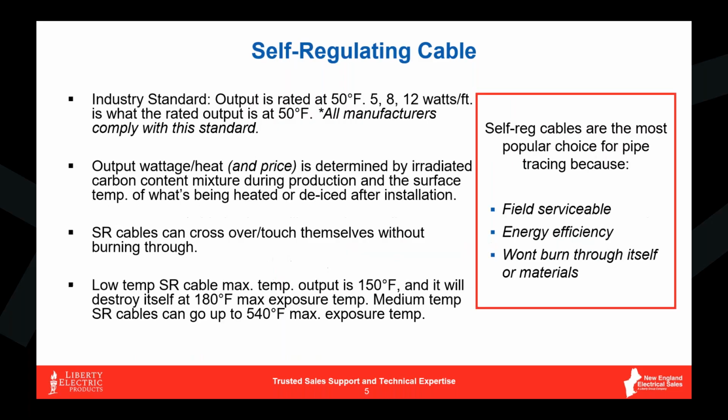So when we talk about self-regulating cables, there is an industry standard that all manufacturers abide by as to how much heat this cable puts out at the temperature rating of 50 F. So when you see the jacketing of a self-regulating cable where it denotes 5 watt, 8 watt, 12 watt a foot cable, that is what it's delivering at 50 degrees F.